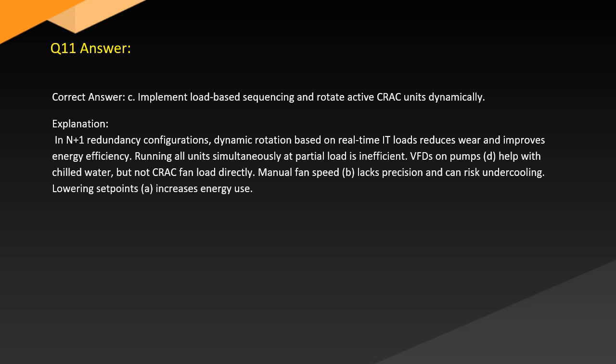Running all units simultaneously at partial load is inefficient. VFDs on pumps, D, help with chilled water, but not CRAC fan load directly. Manual fan speed, B, lacks precision and can risk undercooling. Lowering the set point, A, increases energy use.